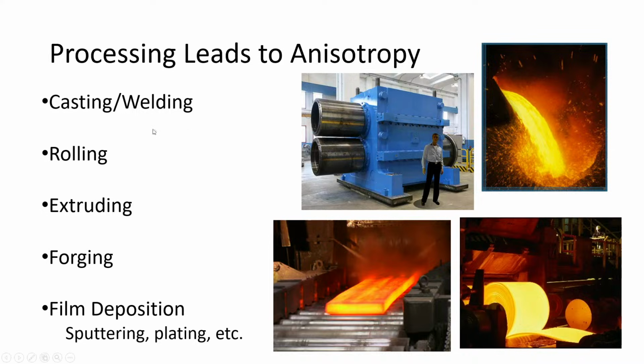But it doesn't matter how we form materials, we get texture that develops. Even if you're doing films, sputtering a thin film, for example, if we're doing an FCC material, then surface energy minimization will dominate the structure, and we'll have 1-1-1 in the surface plane.